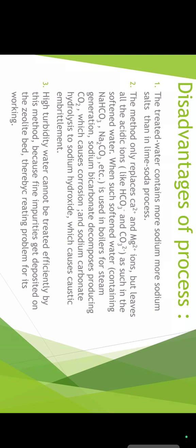Next one is the disadvantages. Disadvantages of the zeolite process. Turbid water cannot be treated because it blocks the pores of the zeolite bed. Second, acidic water cannot be treated because it decomposes the structure of zeolite.